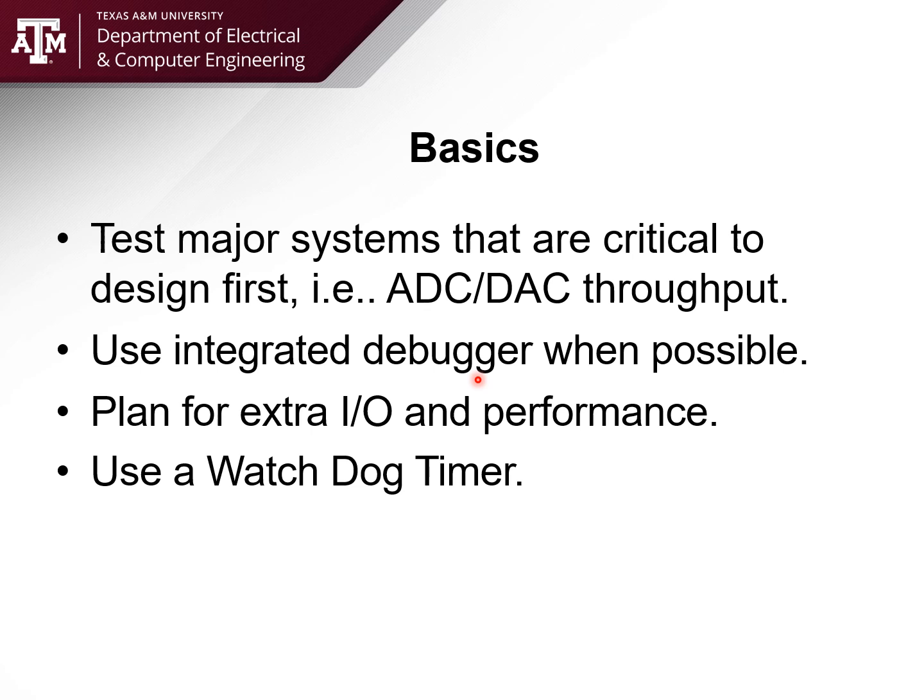Nowadays, you can do things called watch variables, where you can actually stop a microcontroller and read the variable contents right then and there. You can put stop points. You can put all sorts of conditions on a microcontroller, which is very useful. This is all now built into almost every microcontroller. So please make sure you use that if you're doing microcontroller design.